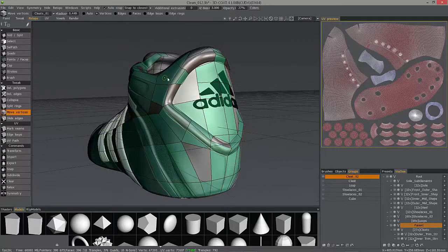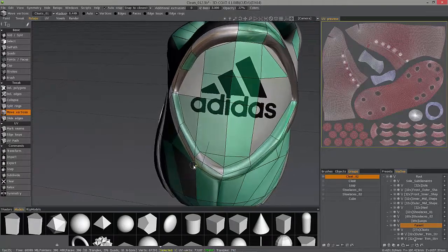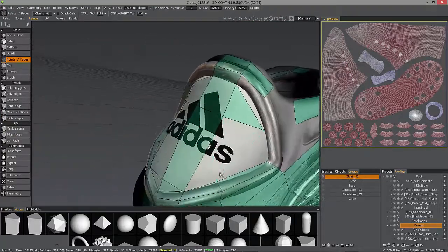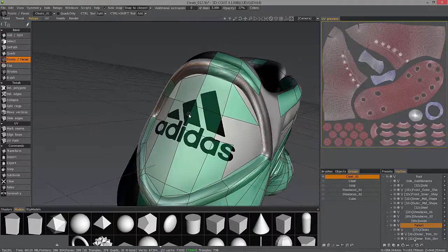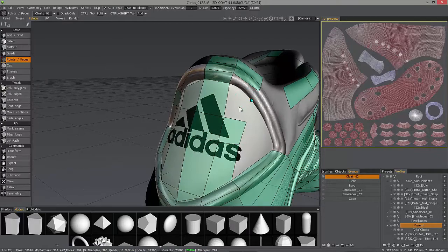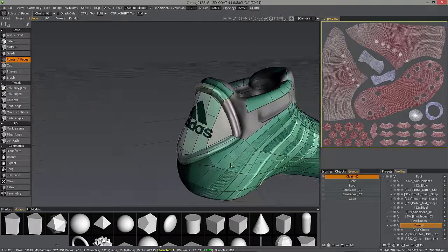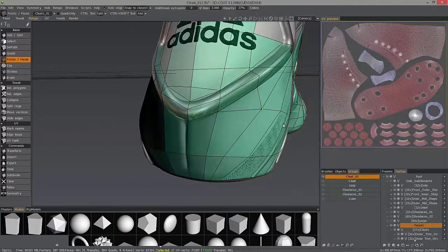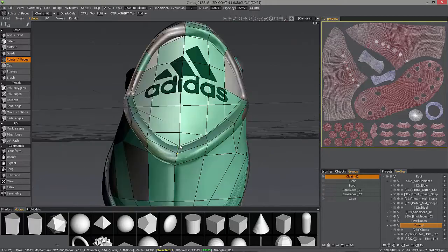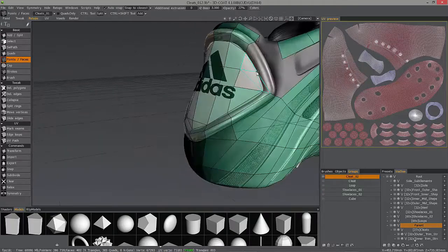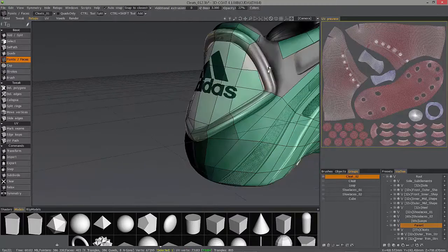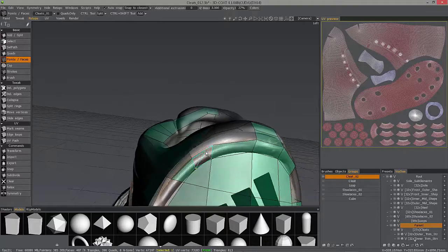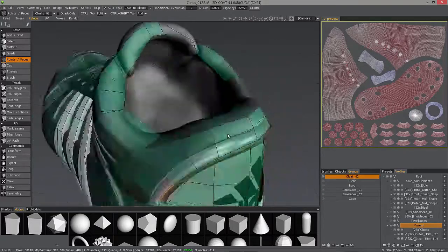And at this stage, I'm still thinking about how I'm going to lay this out here in the back. For the most part, I've got everything the way I want it in the front half, but here in the back half, I still have to piece this puzzle together. And here I'm using the Points and Faces tool. You can simply hover over the center of where you want to lay your polygon down if it has 3 or 4 edges, and 3D Coat will show you a little blue preview, and once you see the preview that you like, you can just right click and it will create the polygon.